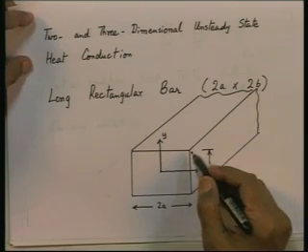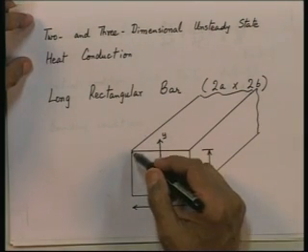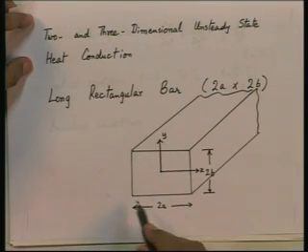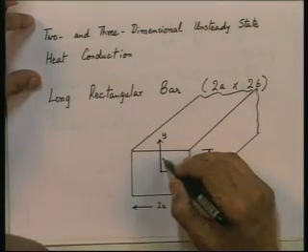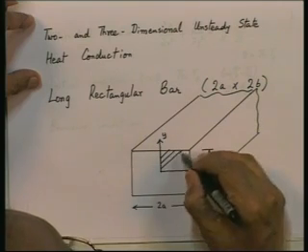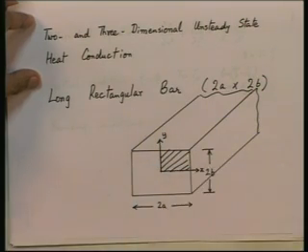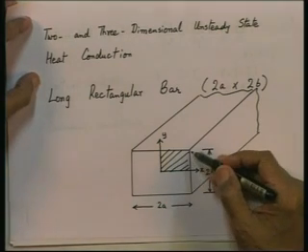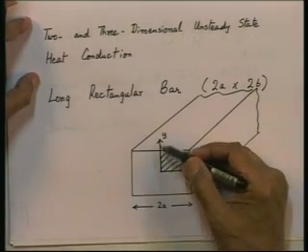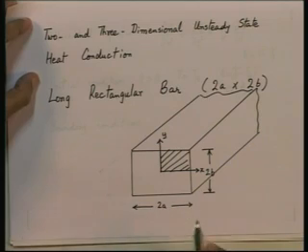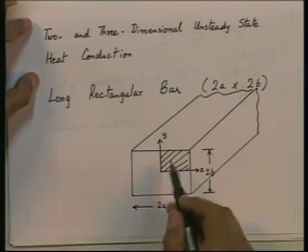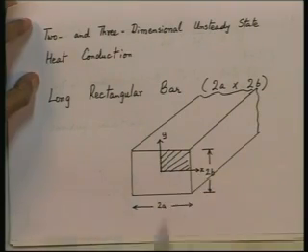We can either put down boundary conditions at x equal to a, x equal to minus a, y equal to b, y equal to minus b, or recognizing that there is symmetry in this problem, we say let us solve the problem only in the positive quadrant, in which case we will put down the boundary conditions at x equal to a, x equal to 0, y equal to b and y equal to 0. If you recognize symmetry, you need to solve only in the positive quadrant. So, we will put down boundary conditions at the 4 edges of this positive quadrant.